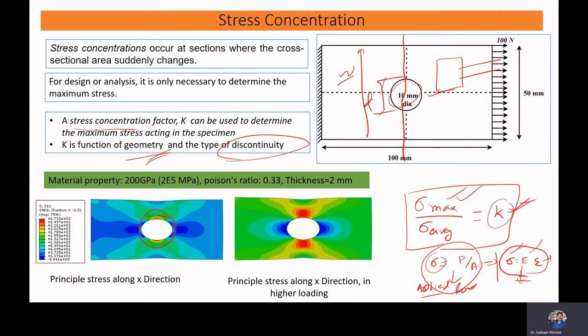Depending on that, we can have different stress concentration factors. So stress concentration factor is a function of geometry, not a function of material property.